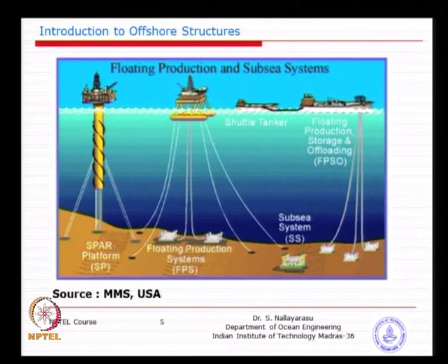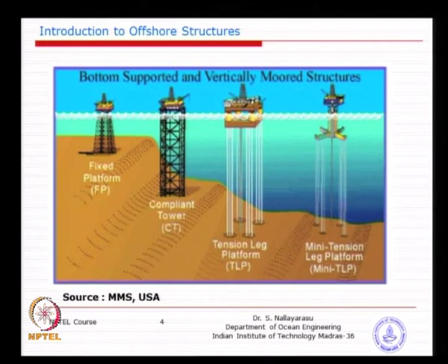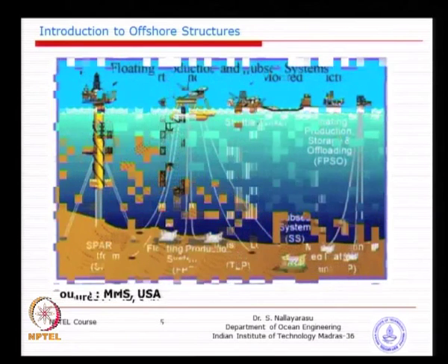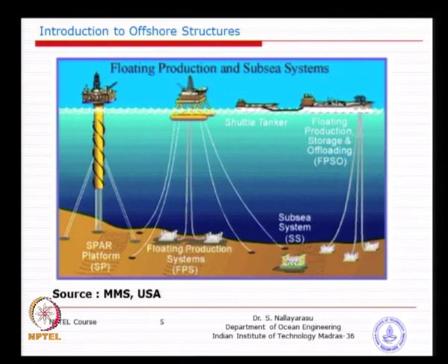The other form of hulls, which also gives you an idea of change in concept, instead of very shallow draft hulls like what you saw in the previous picture, something like this, you see here the deep draft hulls. We call them DDF, deep draft floaters, a vertical cylinder floating upright with a specific means of design. You could see this hull also moored vertically sometimes, or with slant lines, either taut or slack, but you could see that the stability is coming from a single leg.